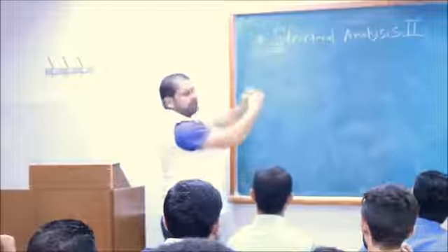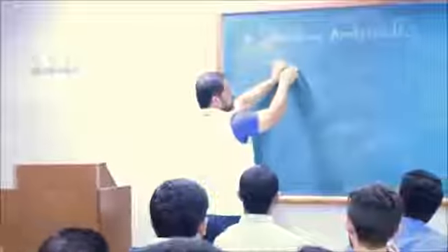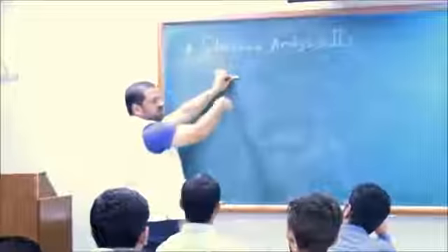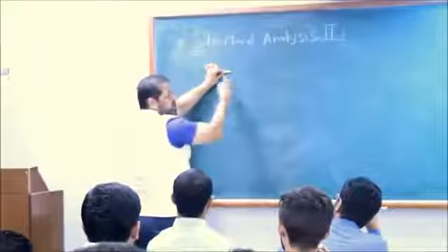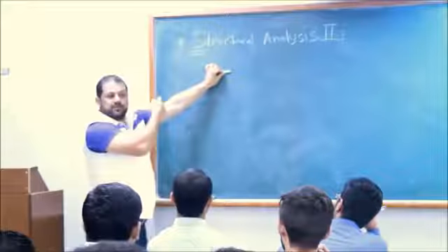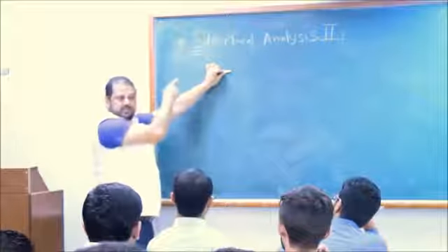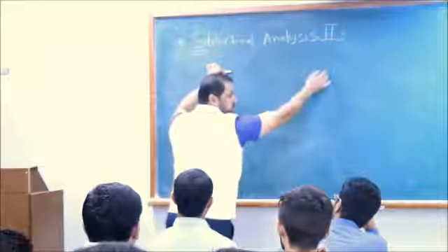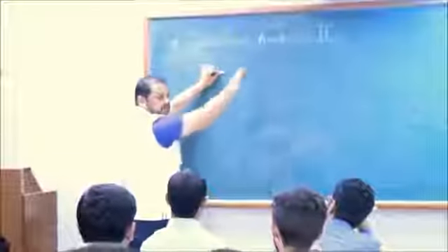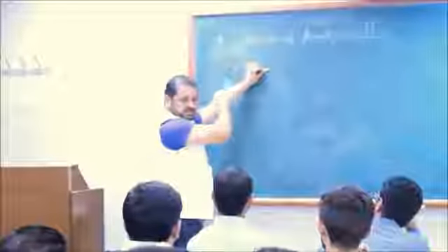It means someone will put a piece of wood, nail it in the wall. If you just apply any kind of rotation, it will rotate. It will not move in the Y or X direction, but it will rotate. So one pin at one end of a member is not enough to provide stability. There is rotation. That's why we have a pin roller to create semi-support or something. Or you can fix one end. Then it will not rotate. No translation in the Y direction, no translation in the X direction, no rotation.